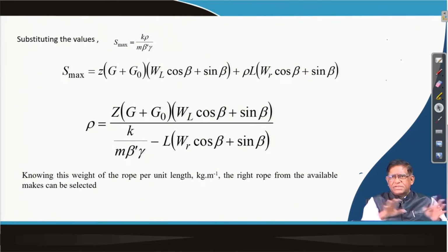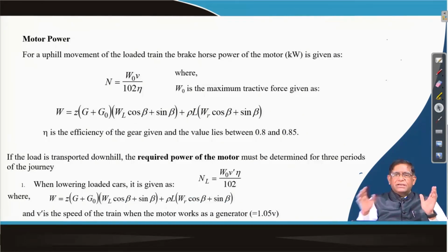So, that is a very basic principle: while doing this application of wire rope, you will have to determine the material specifications, or you need to check that whatever rope you are purchasing, whether the right material has been selected or not, that is, the density depending on the breaking strength will have to be found out. That selection is important.